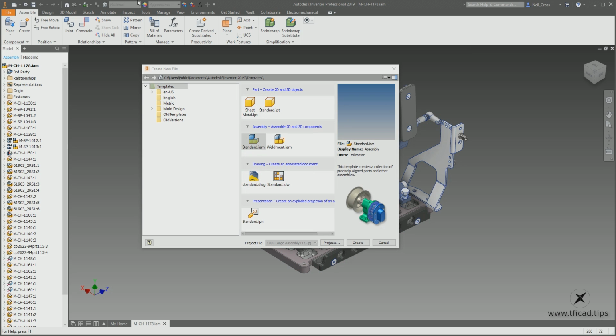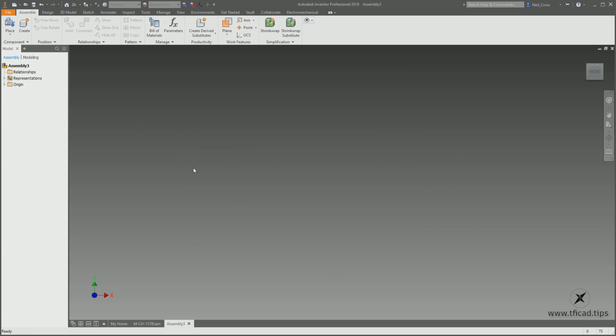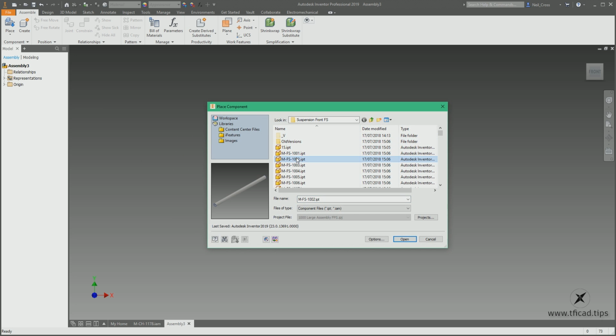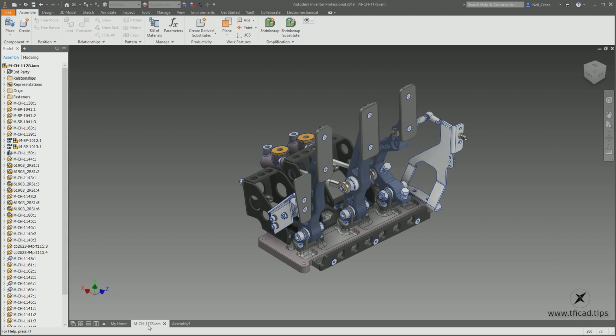And then what you do is you go over to Inventor, and then you start an assembly, which is empty. And you don't model anything in here. What you do is you just say, I want to place an IPT into the assembly, and you take all of the parts that you've modelled separately, and you put them into the assembly. And then you constrain them together. You push face to face, and put a pin through a hole, and they're called constraints. But yeah, in essence, the assembly is made up of a collection of parts.